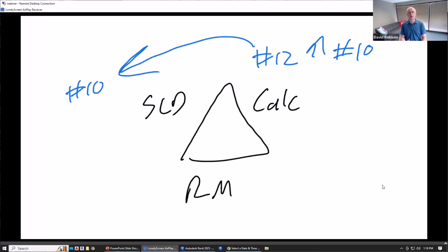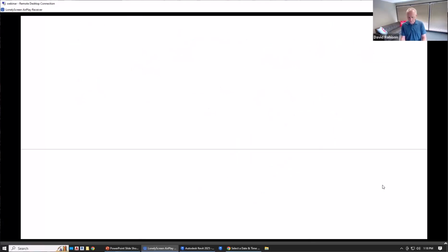This obviously is not a feeder. It's going to be some sort of branch circuit, but that's feeding a piece of equipment. You want to make sure that that has the right size to that piece of equipment. And then in the Revit model, if that's showing up anywhere in your panel schedule or on a home run, you want to make sure that that shows up there as well. So anytime you make a change in that calculation, you need to think through, get it in the single line diagram and the Revit model. Something like a voltage drop wire upsize, you need to get that in the other places.